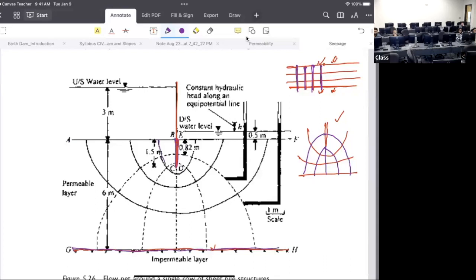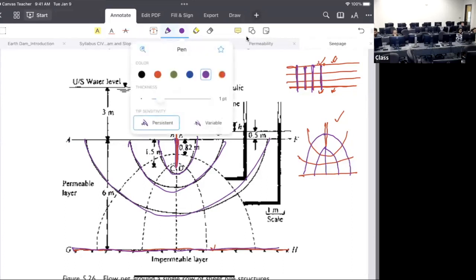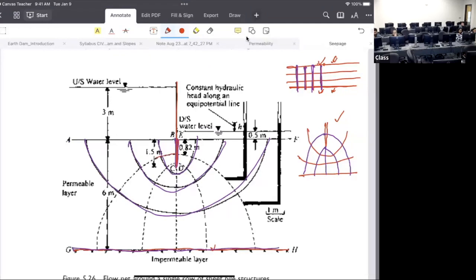So now if we come here, we get our outer lines. Our flow lines will be parallel, right? These are parallel lines. Correct? And then our potential lines are perpendicular, cutting each line at 90 degrees. Isn't it? If we have that, then all we have to do is what? We need to find out the I. How can we get the I?